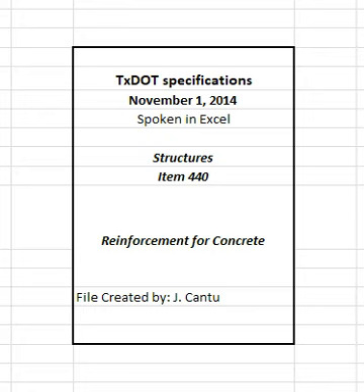Bend stainless reinforcing steel in accordance with ASTM A955. 3.2 Tolerances. Fabrication tolerances for bars are shown in Figure 1. Figure 1. Fabrication tolerances for bars. See figure in specifications. 3.3 Storage.